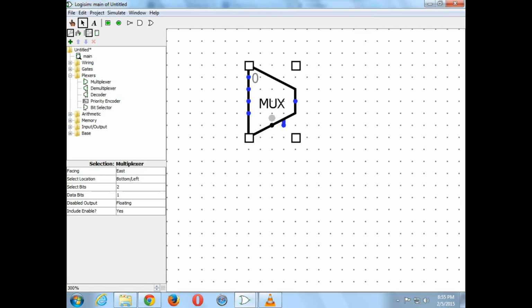Now the other one is data bits. The way it is right now, we have one physical wire going to each of the input points. So it's only good for switching from 4 input alternatives to 1 output bit. So this is one alternative, 2, 3, 4. So you can select one of the 4 sources and connect it to the actual output. But it's 1 bit only.